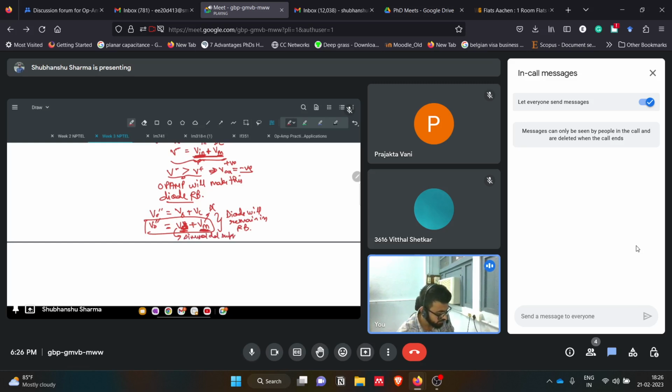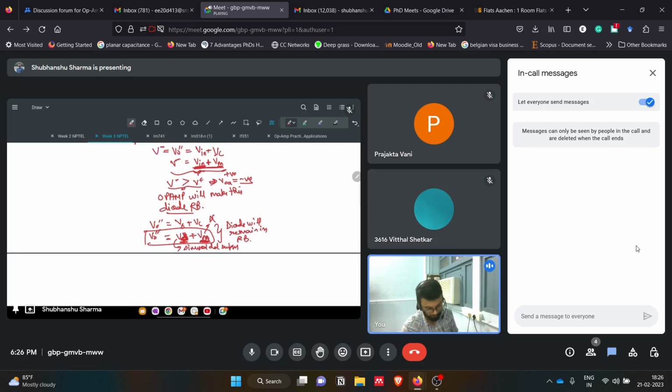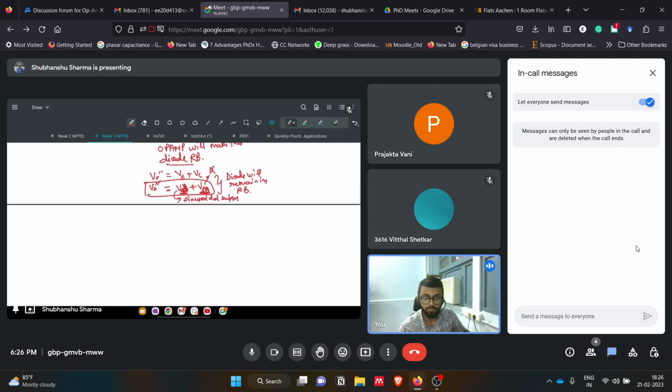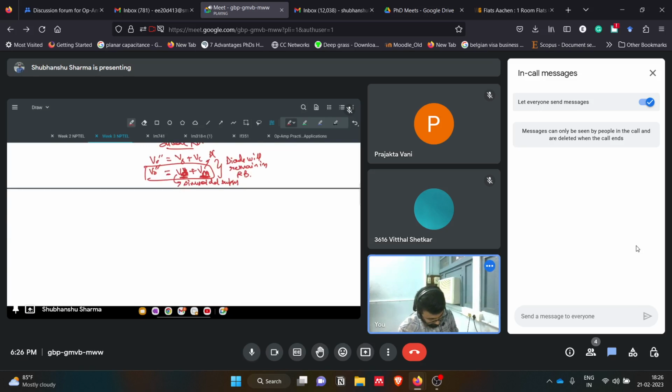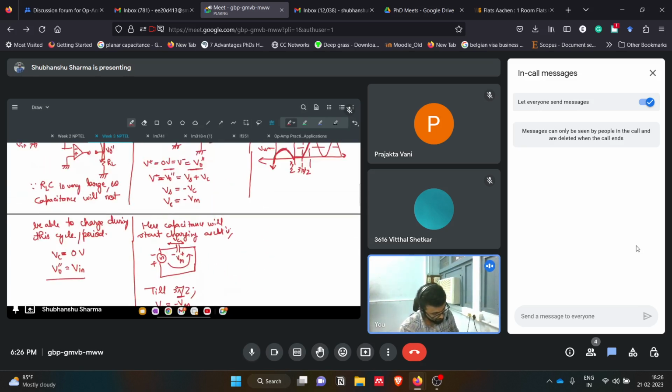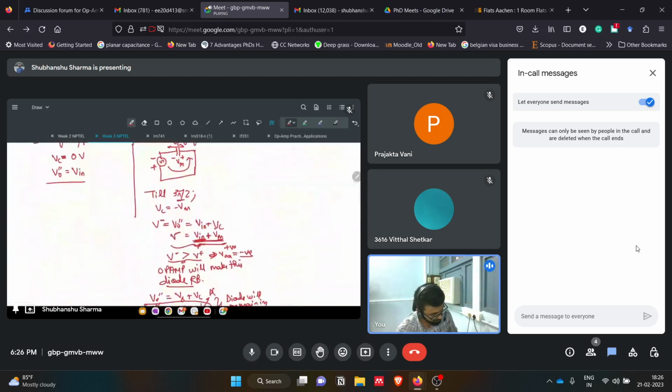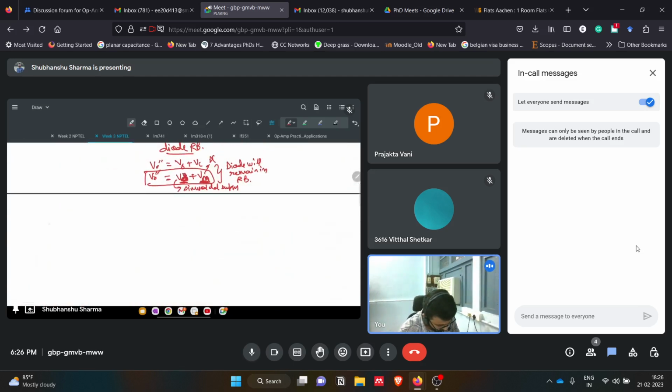So we added basically DC to this Vs, so we got a shifted waveform. Since we use the superposition principle, we also have to consider this Vref, which we initially used here. Now combining, what will be the final output? V naught will be V naught prime plus V naught double prime. This is because of Vref, and this is because of the sinusoidal supply.